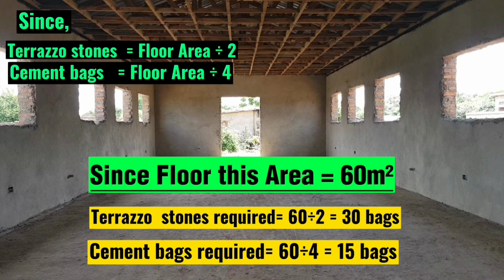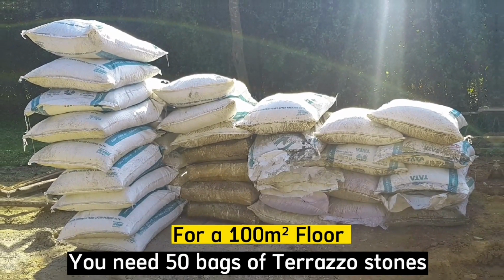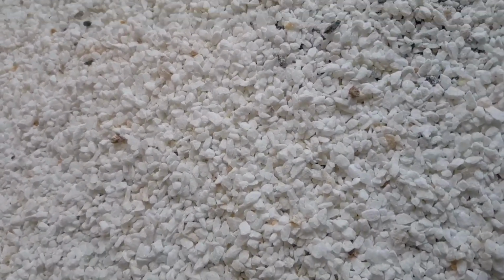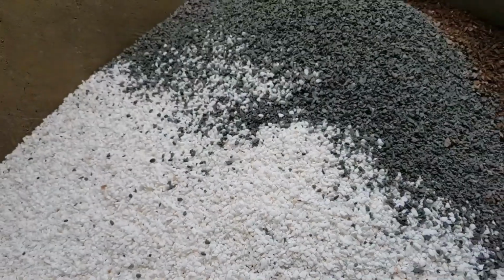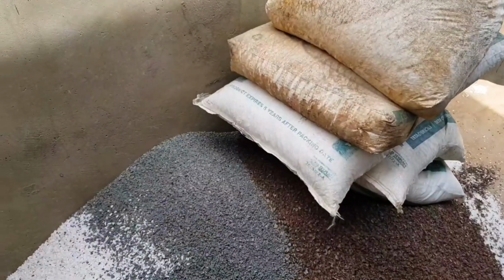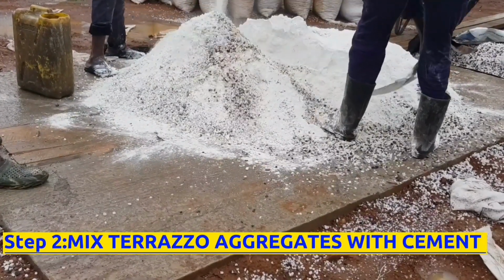When you have a 100 square meter floor, you need 100 divided by 2, which gives you 50 bags of terrazzo aggregates or stones and 25 bags of cement. As simple as that. This is a proven accurate formula for estimation of terrazzo flooring materials. In fact, it has been tested on a number of construction projects and it has worked out very accurate and perfectly.